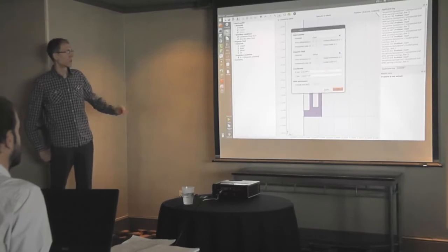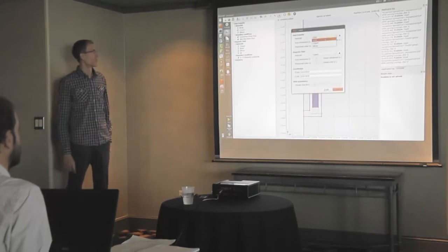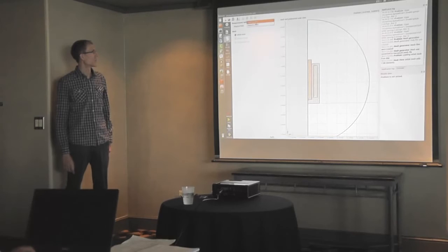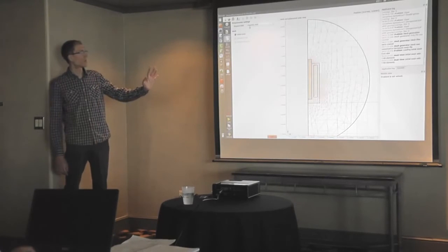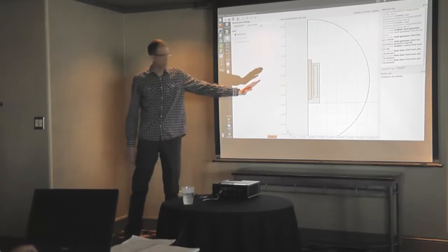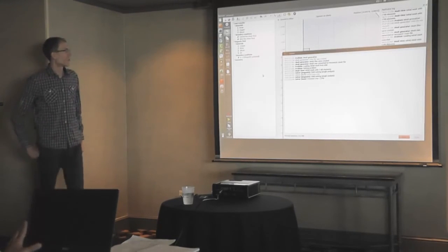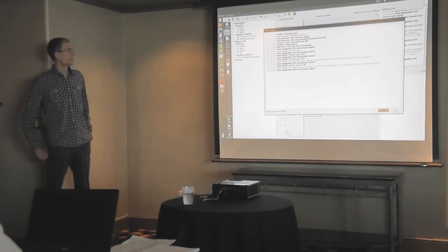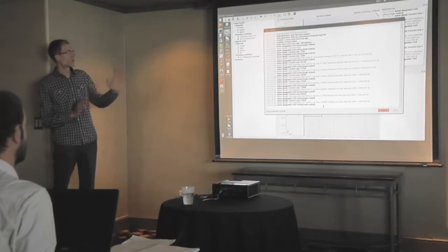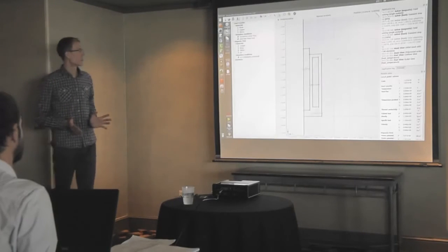Assign again the materials and the domains. You can see different meshes. This is for magnetic field, where we calculate in the whole domain, and for the temperature field only in this part. It's the physics for the program. Now we started the calculation, which will take more time because first we have to calculate the magnetic field and then the transient analysis for the heat field.